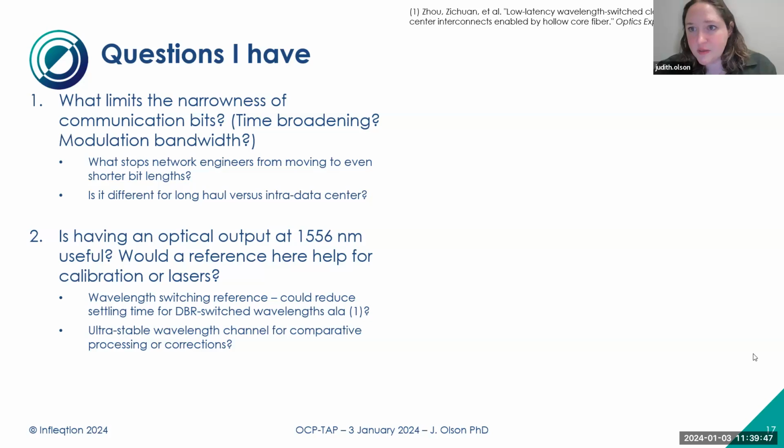I wasn't sure what level of calibration or characterization is even done of the wavelengths being used when you're dividing things into wavelength channels. You know, how careful do people need to be? Do you care if there's an offset? Do you care if there's breathing between the channels where they're all moving apart from each other? Or is that just carried in the guard bands?